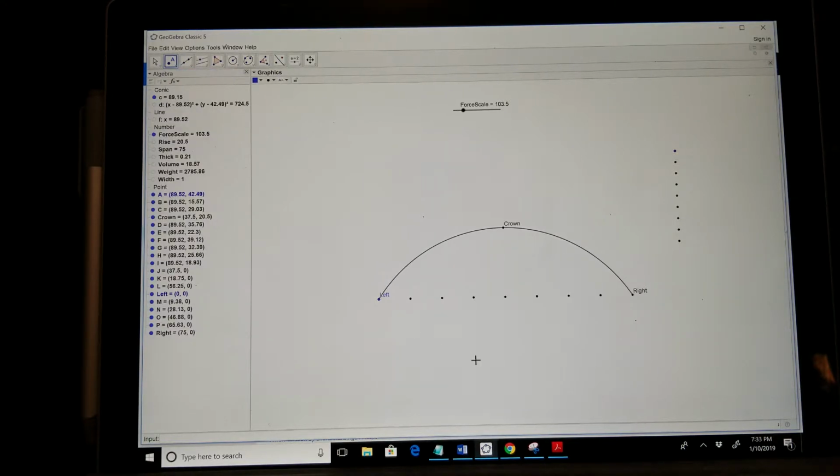Now the next step is just a little tricky. I have a load and I want it to be right here at the centroid of that segment, and I want the next load to be right here at the centroid of that segment. It's like a uniformly distributed load on a beam. You smear it into one concentrated load at the centroid. So I want to find the centroid of these segments, which is obviously I will use the midpoint, but I don't want to make a mistake.